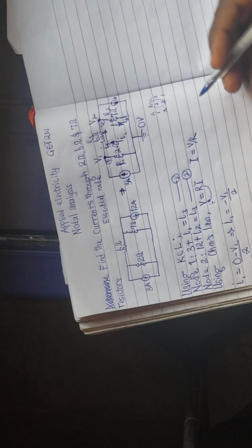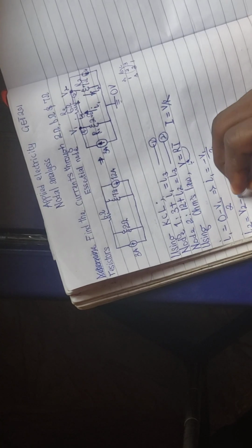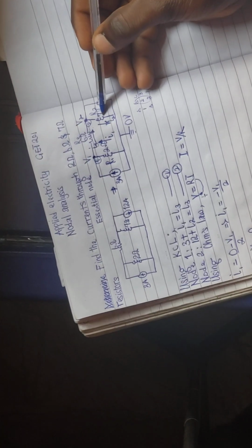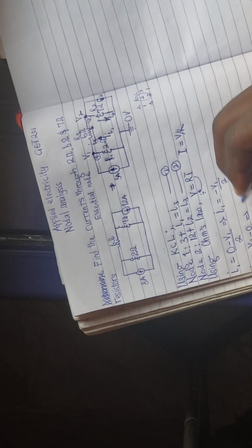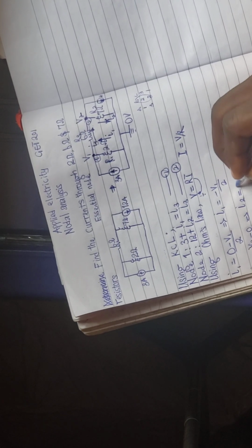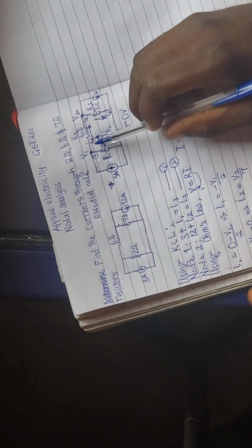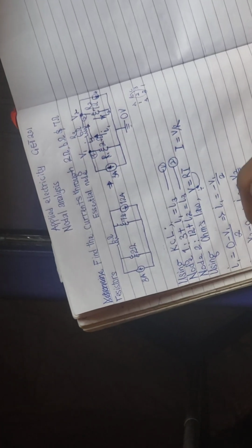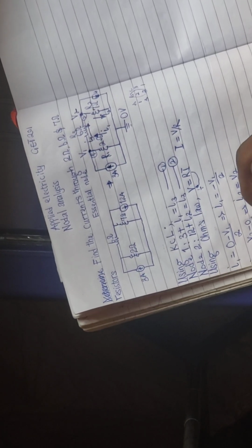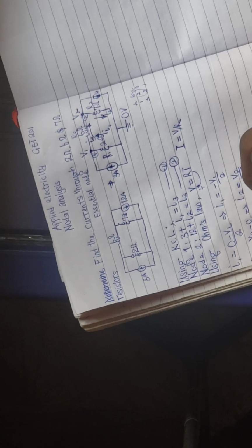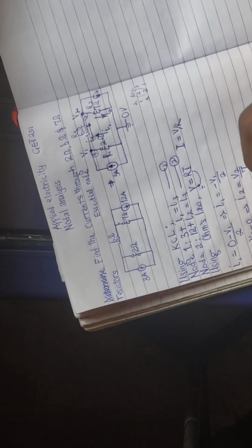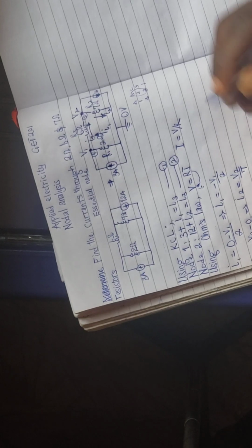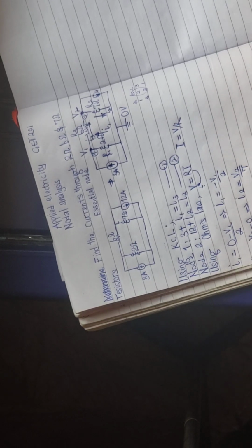That's V2 minus 0, over, look at the resistor. I'm working on the resistor. The resistor is 7 here. So I2 is V2 over 7. The next one is the current going from this side to that side. So we have I3, that is V1 minus V2, over 6. So that is it. It's still correct, so I don't need to simplify anything. This is just direct.